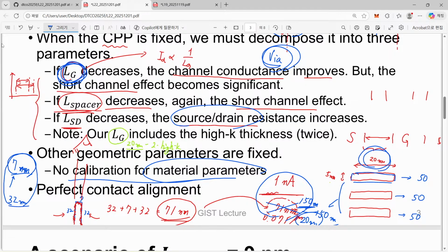I don't think so, but this is the convention. So please do not be fooled by really high values of reported normalized drain current when you look at the gate-all-around transistor. This is the real convention currently used in the industry.